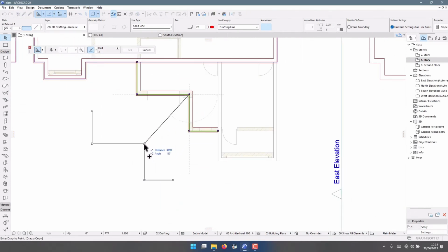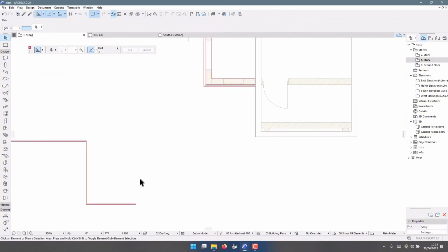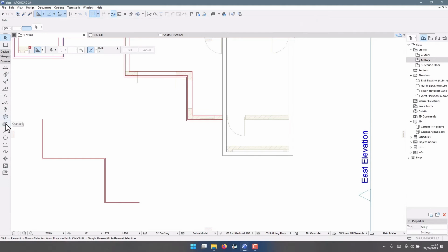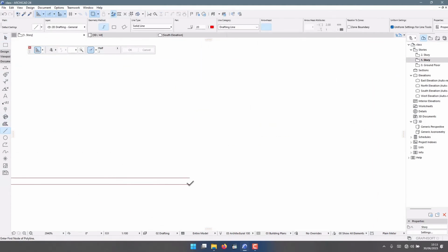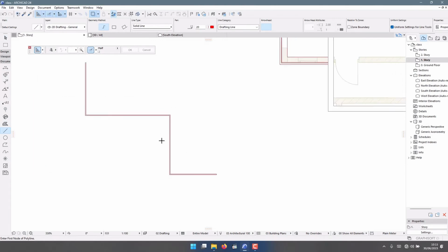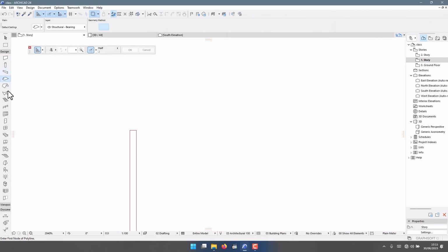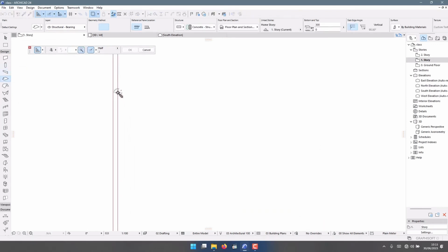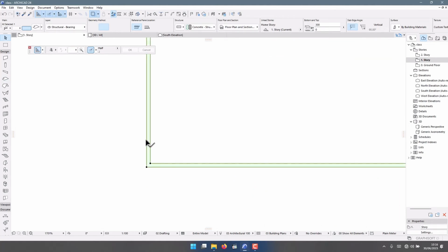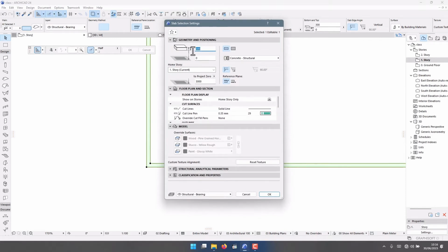Let's bring it here. So you have to close the ends first. Also same to here. Then you click on the slab tool, you click on here, or you hold space bar and you click once. You click on it again. Can we use a different texture? Yeah, Ctrl T. We want it to be 75. We want it to be C06. Okay. Then we can take it back.